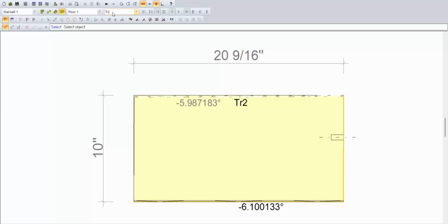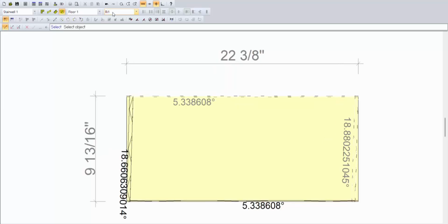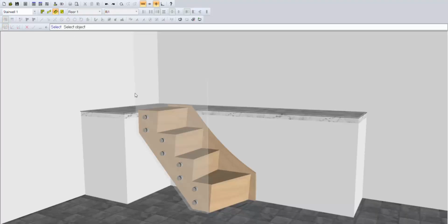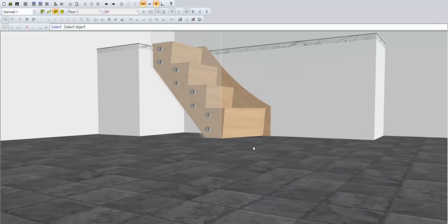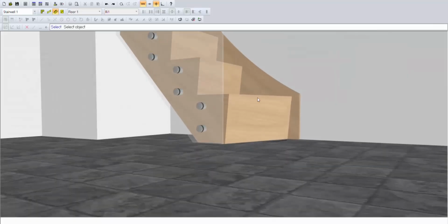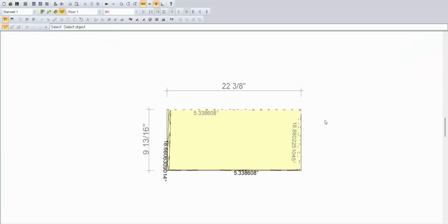But the riser, if I go here, this riser is totally out of any angle, because if you look in 3D, and that's maybe part of the reason I wanted to show this, if you make a stair like this, you can imagine if you have to make this part, it's angled on all sides differently, and it's even not 90 degrees. So all these angles we get calculated, and we can just run it on a 5-axis automatically.